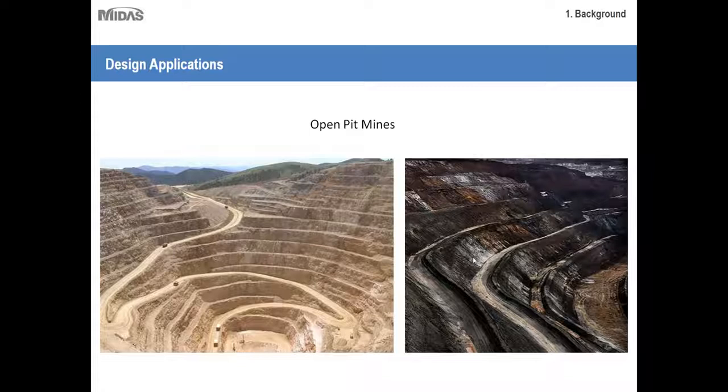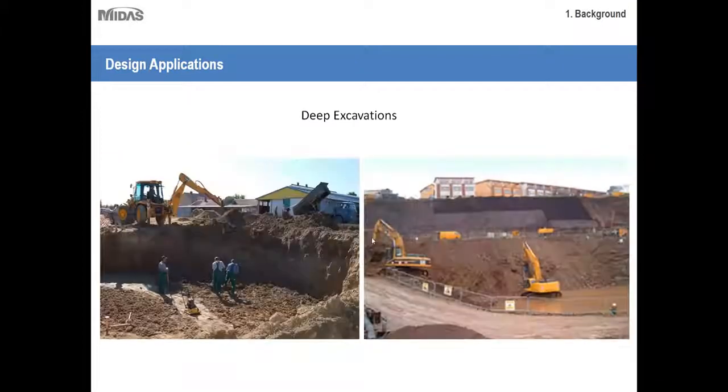So once again, if water is being stored in your slopes, that can cause a certain amount of weakness. So ideally what you'd want to do is drain your slopes before building them. That way they'll be very stable. For those of you who are involved in mining, I'm sure this type of slope stability analysis is familiar to you. Okay, then also we have deep excavation.